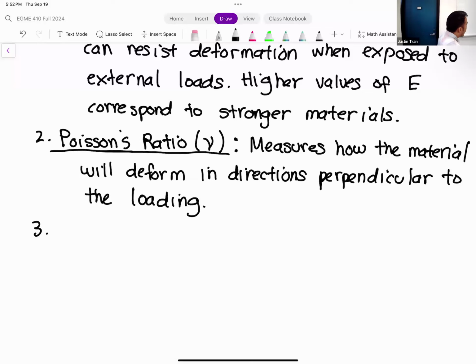So those two are, I would say, the strictly required material properties, right? If you recall from activity 2, the two properties that we specified when we defined our aluminum material properties were just the Young's modulus and the Poisson's ratio. Technically, there are other properties as well, but a lot of times we compute these other properties from these two.